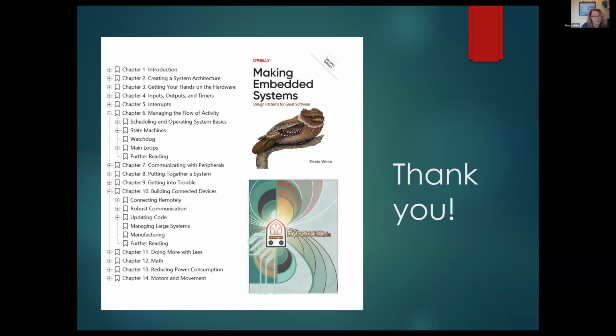They may be slightly slower than what you could build yourself, but the speed gain you get from having it all be done and tested is 100% worth it. So use the HAL libraries. If something needs to go faster or needs to be optimized, deal with it then. Don't write that code from scratch. It's not worth it. And HAL is hardware abstraction layer, because I didn't do a good job of starting that one.